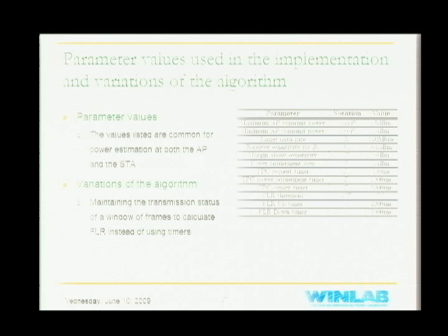This is because there have been studies in the past which have shown that the number of power levels that creates distinct RSSI variations in indoor environments is 5 to 6. And even in Symphony and many other rate control algorithms, they choose to use 3 dBm as the threshold for effecting transmit power control changes. We use 2 dBm based on empirical measurements, as this has proved to be a better estimate to use.